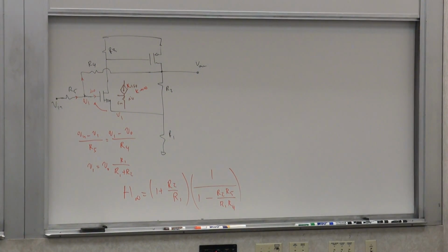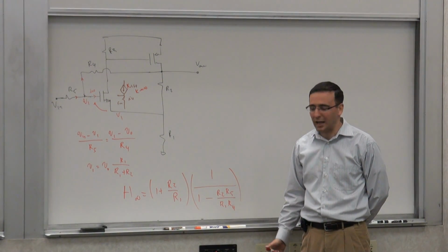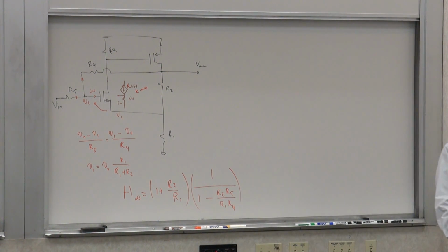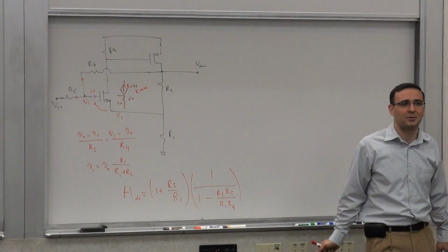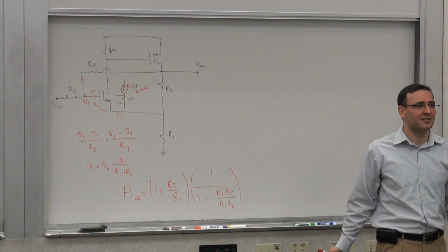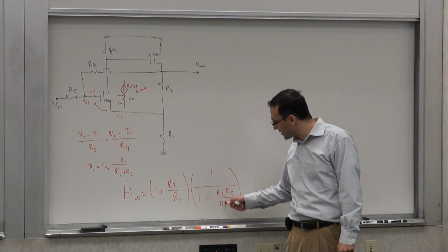What can you do? Oscillation? No, forget about oscillation before we get there. Let's say I'm going to use this as an amplifier. Even at low frequency, I can increase my gain, I can boost up my gain. This is how people used to increase gain in the old times. Positive feedback was used before negative feedback, actually. Because when gain was scarce, people said, why on earth would I want to use negative feedback to lower my gain? I'm using feedback to increase my gain. So this way you can make this, for instance, 0.9.